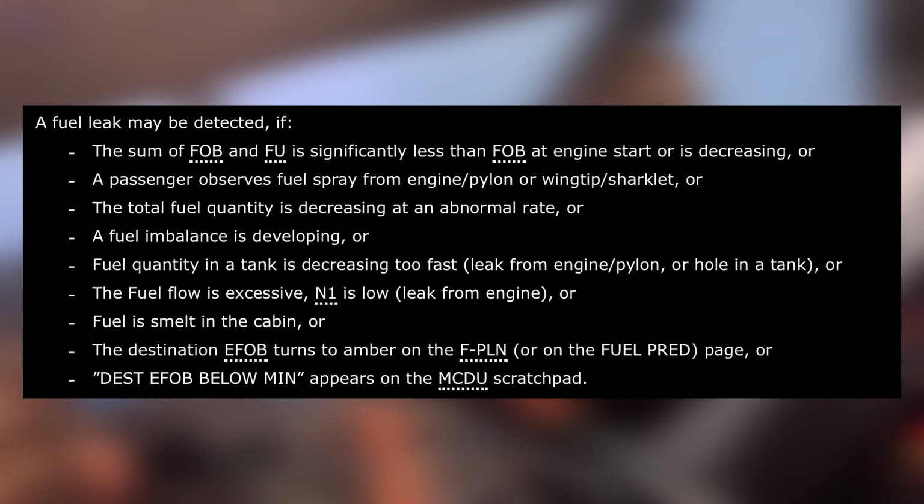As for John, he reaches the fuel leak conditional statement. He will diagnose if there's a fuel leak to determine whether or not the subsequent ECAM actions apply. Here are the different means our QRH provides to detect a fuel leak. An appropriate means to go through the identification at this time is to add fuel on board and fuel used. The sum of these two numbers should be close to the fuel on board at engine start.